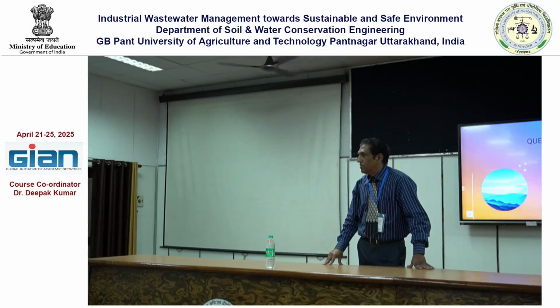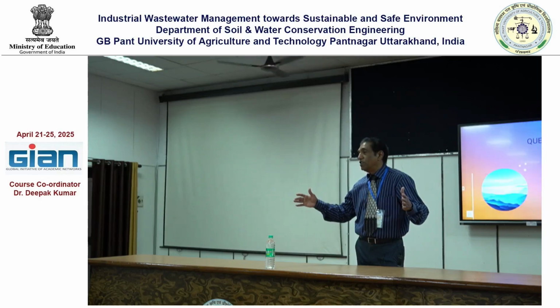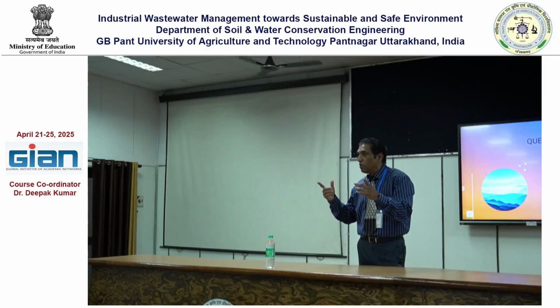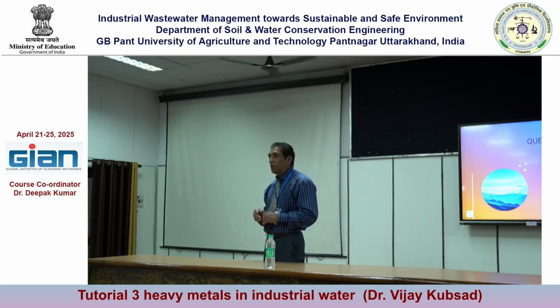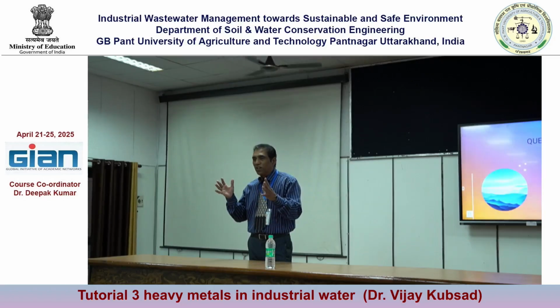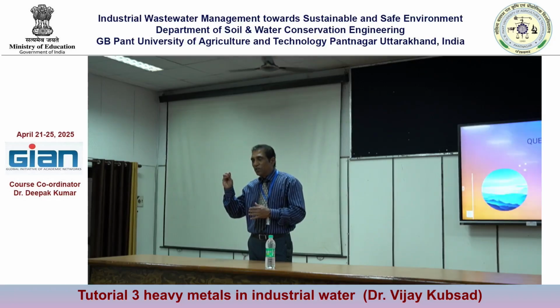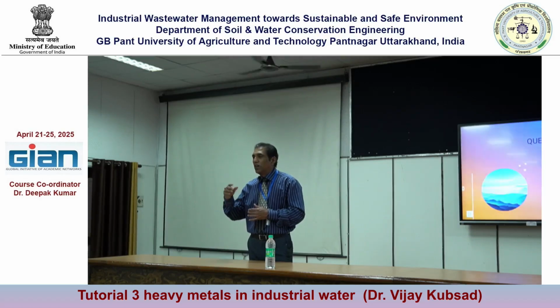And there are industries producing very low BOD and high pH, and some industries producing low pH with organic compounds. You will mix all that in an equalization tank, and neutralization occurs. If a food industry is there, their BOD is quite high. You need BOD. Industrial discharge always has less BOD, so we look for a higher BOD. Industries producing higher BOD, where a lot of microorganism food is coming ready-made, help. And other industries, if a toxic metal is there, will have to remove it and then discharge.